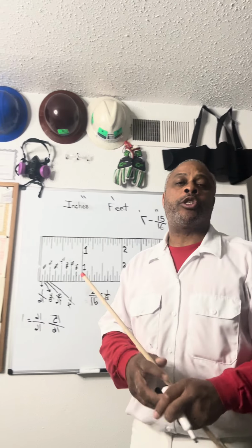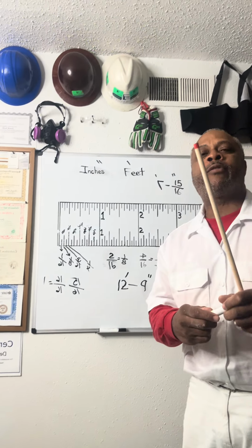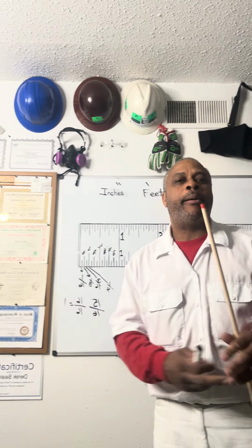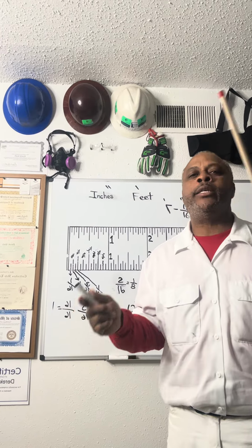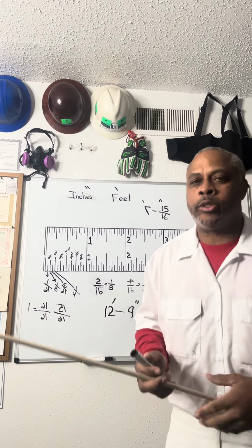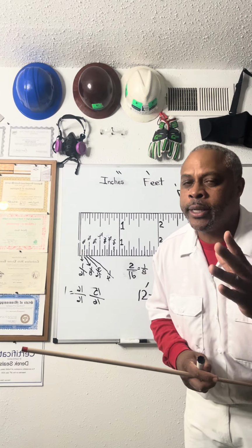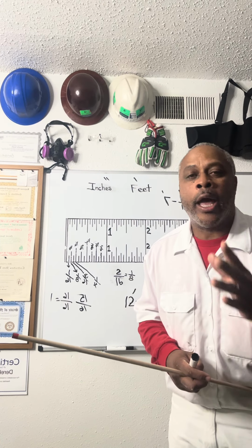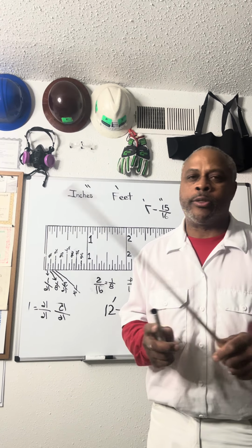And then you might have lumber that you're probably going to have to cut from that's random length. There might be 10 footers. And he may say, okay, look, I know we got waste, but we need studs. We ran out of studs on the job. Your job is to go cut 50 because you need 50 2x4s at 104 1/4 or 104 5/8. That's the measuring tape, baby.